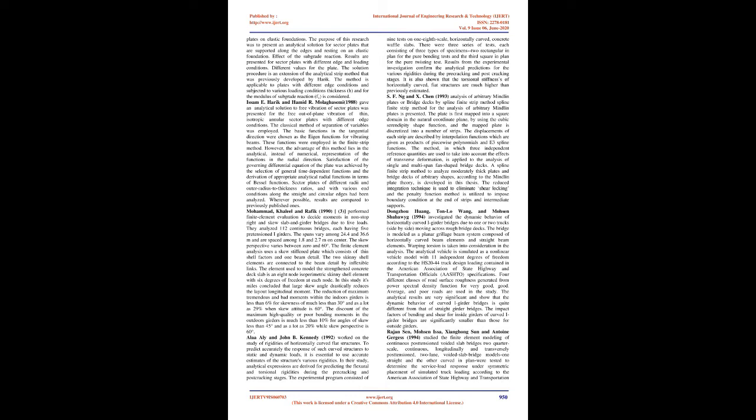The displacements of each strip are described by interpolation functions which are given as products of piecewise polynomials and B3 spline functions. The method, in which 3 independent reference quantities are used to take into account the effects of transverse deformation, is applied to the analysis of single and multi-span fan-shaped bridge decks.